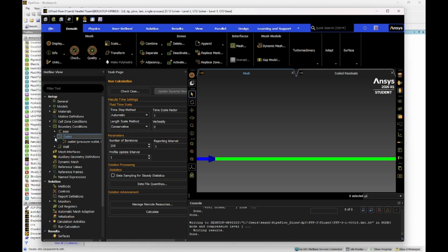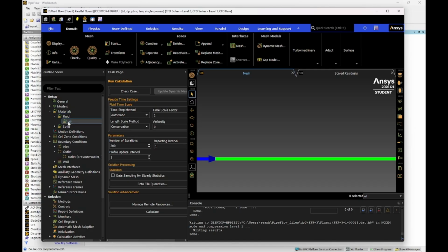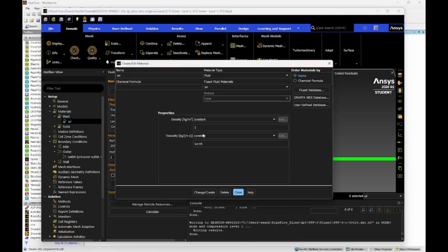And then before I change the wall, I almost forgot, you should go to fluids and make any changes so that your Reynolds number stays below 2300. The lower the better. The closer it is to very low, the more accurate results you'll get.